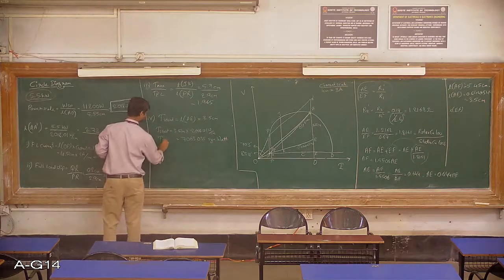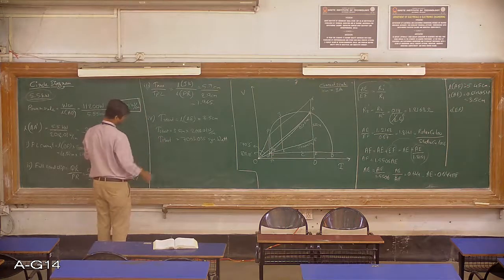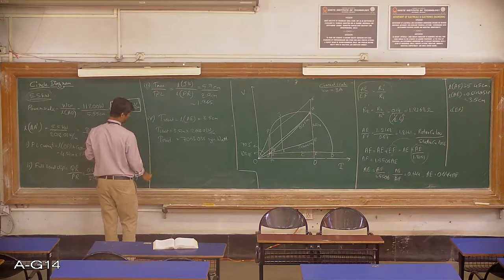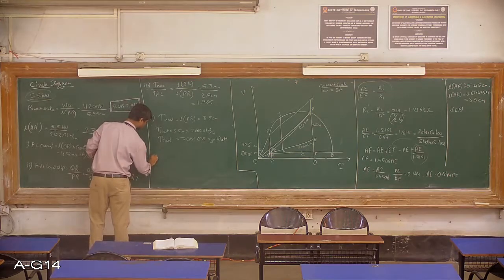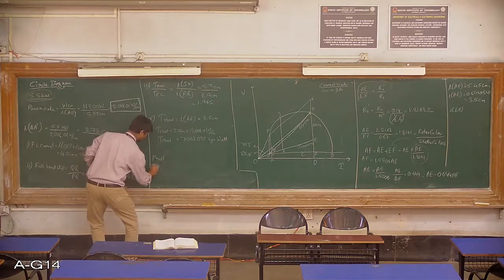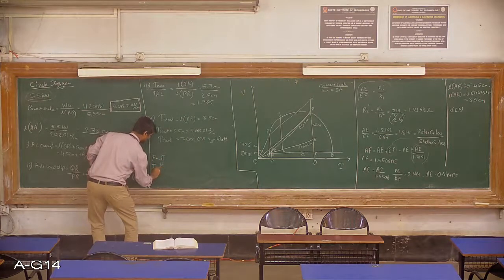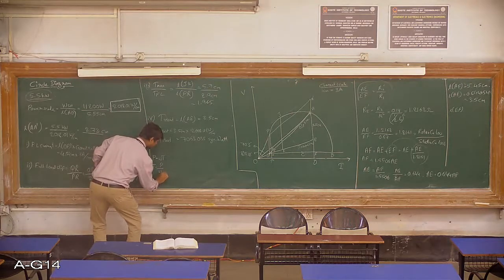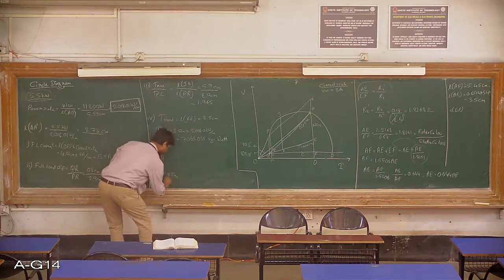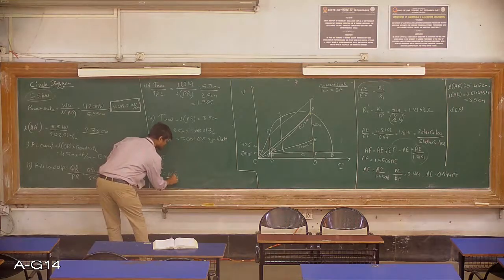Starting torque is in terms of watts now. Okay, but we want the torque in terms of Newton meter. So to convert this into Newton meter, we know the equation that P is equal to omega T, where T is the torque. So torque is equal to P divided by omega, where omega is equal to 2 pi N S by 60, capital N. Ns is synchronous speed of the motor.